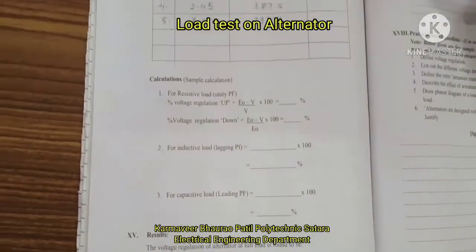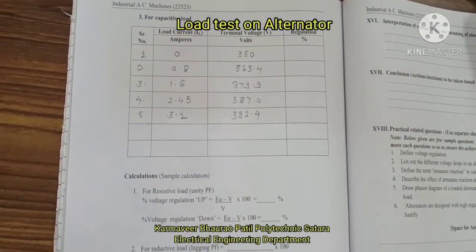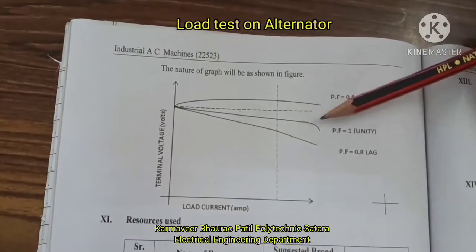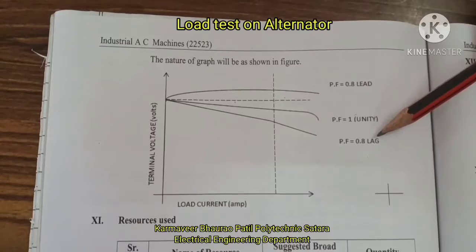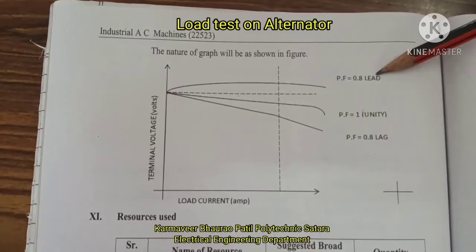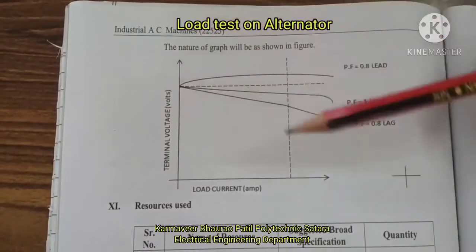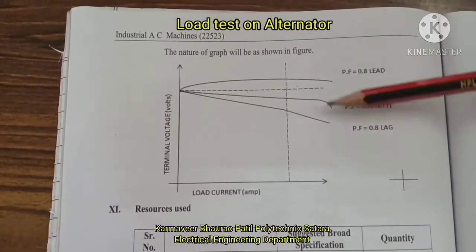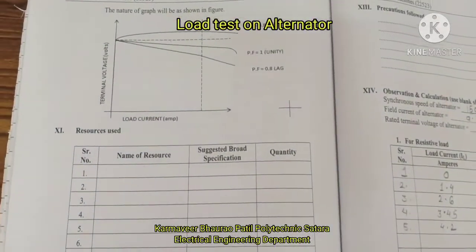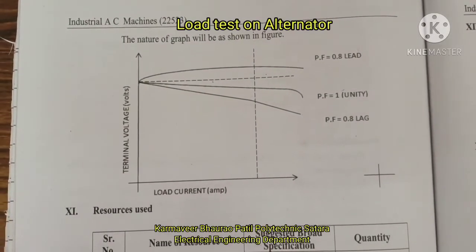Also you have to complete the regulation calculation for each column, and then plot three graphs showing regulation: regulation for resistive load, that is unity power factor; regulation for inductive load, that is lagging power factor; and regulation for capacitive load, that is leading power factor. You will show the graph for terminal voltage and the load. So you have to plot this graph and calculate the three regulations. That will complete the experiment. Write down the question answers, and you will stop the practical here.